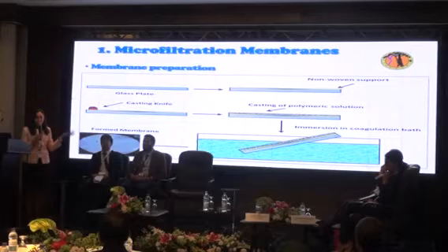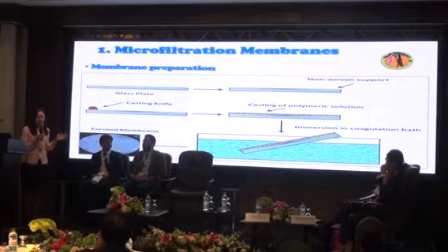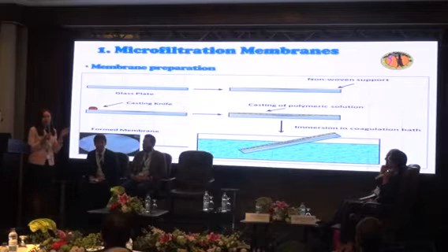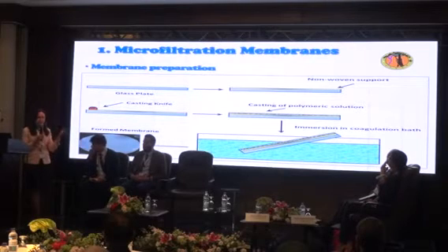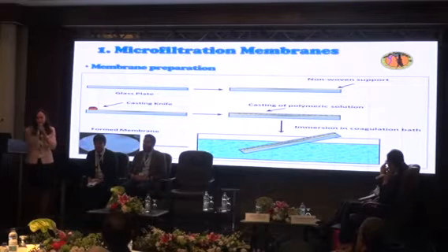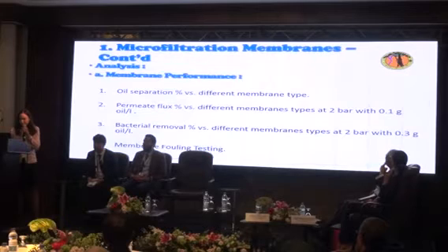Okay, so at the beginning, as I said, for the first stage for the membranes, I use the phase inversion technique to create the microfiltration membranes, and I mainly use polyvinylidene fluoride as the main substance for the microfiltration membranes. And what's new is that I use polyethyleneimine, and I will refer to it in my talk today as PEI, just to be easy to say, with the phase inversion technique.